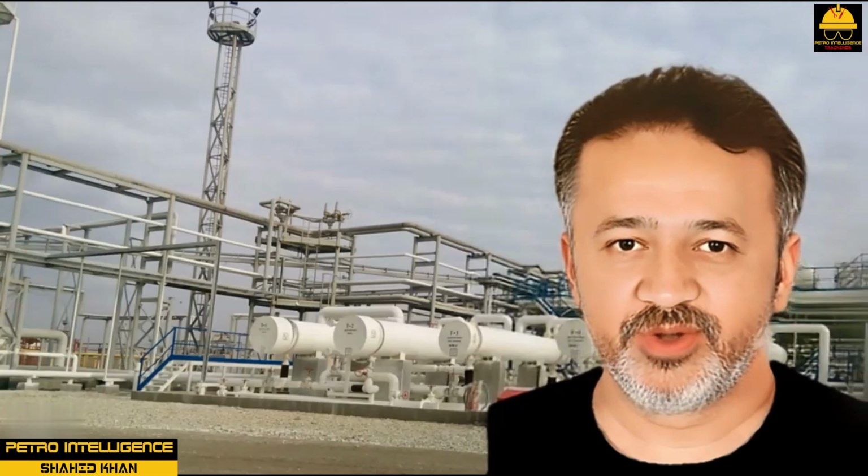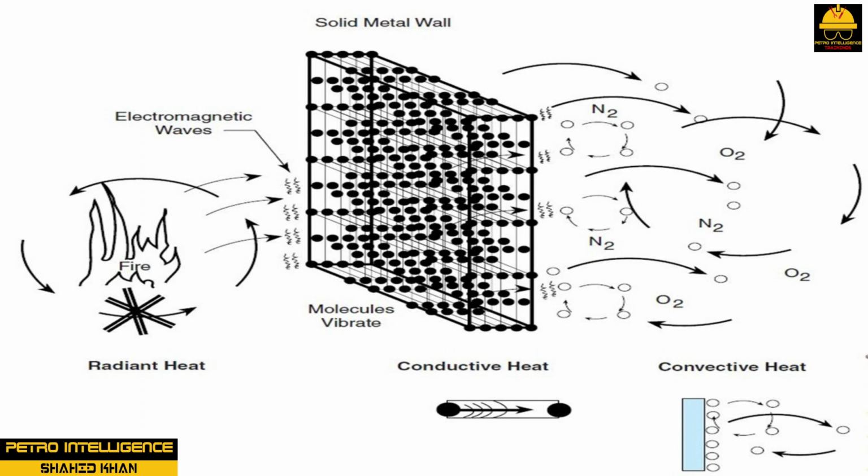Heat transfer and fluid flow. The methods of heat transfer are conduction, convection, and radiant heat transfer as shown in picture. In the petrochemical, refinery, and laboratory environments, these methods need to be understood well. A combination of conduction and convection heat transfer processes can be found in all heat exchangers. The best conditions for heat transfer are large temperature differences between the products being heated and cooled. The higher the temperature difference, the greater the heat transfer, high heating or coolant flow rates, and a large cross-sectional area of the exchanger.